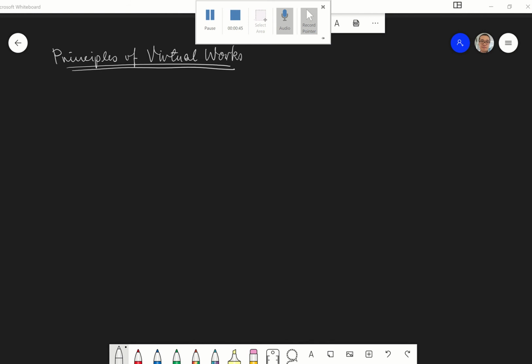Those ways of working out the stiffness matrix don't really help to work out this K matrix for this type of elements. So a way to get around this, or a way to make this more tractable or pragmatic to work out the stiffness matrix, is to apply the principle of virtual work.